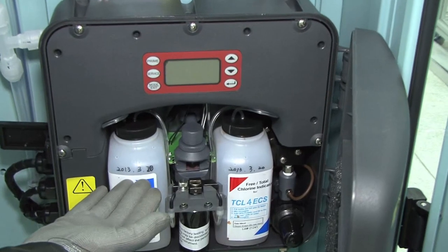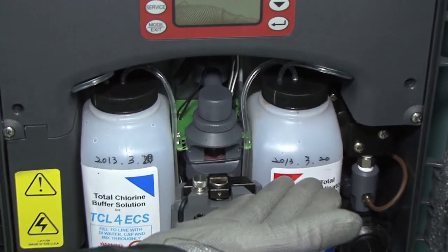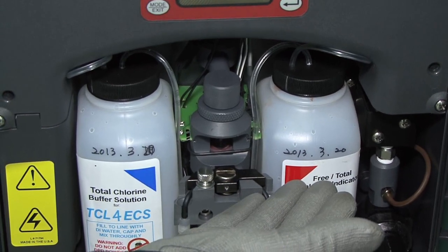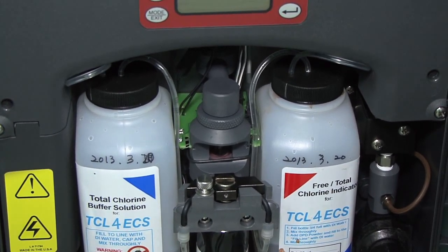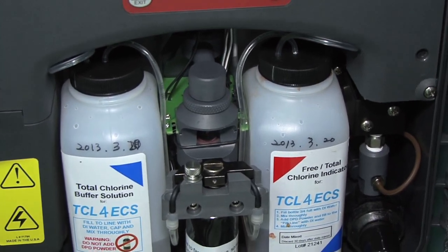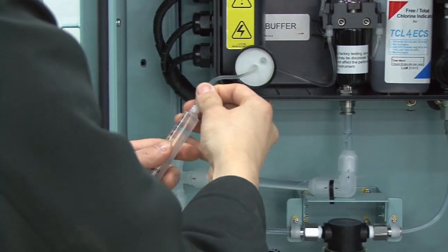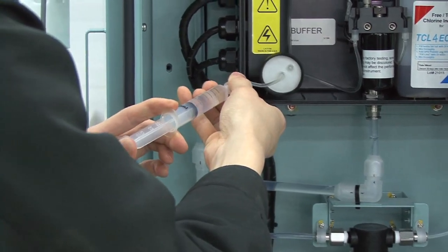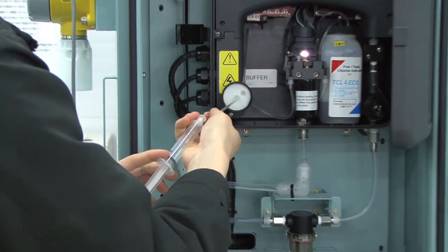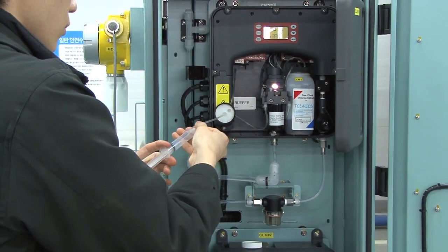2. When the same problem persists even if sampling water flows into the sensor. 1. Check replacement date of TRO sensor. Please refer to checkpoints before operation, selecting remote mode and checking supplies, Step 3. 2. Make sure to prevent air coming into the tube between CLX and the sensor when replacing the solution. Please refer to replacement of supplies, replacement of CLX reagent. If the same problem persists, please contact the manufacturer.